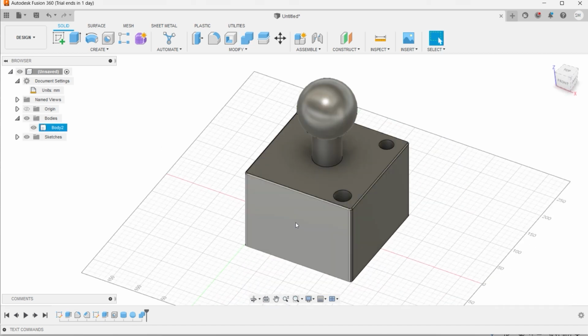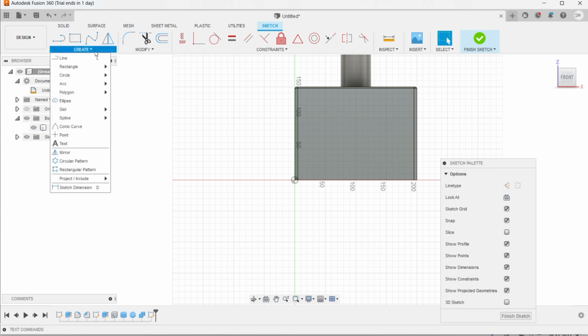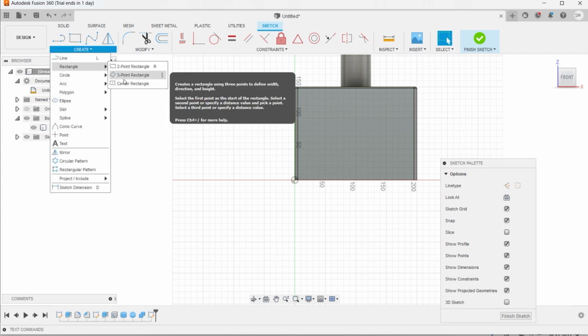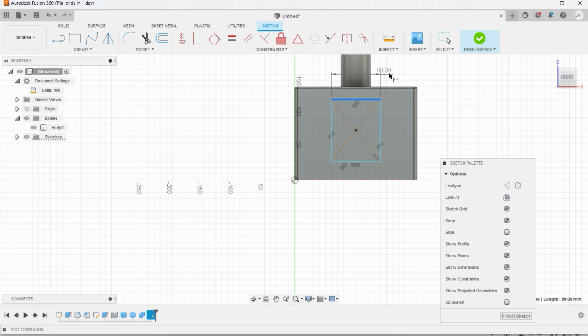Suppose you want to make one object here itself. Let us select that space and start sketching on the surface. I want to make one rectangle. It will be center point rectangle. You can make anywhere else, right? We made this one, and we can put smart dimension to this one with a D. This one equal to 80 millimeter, and again this one can be 90 millimeter. We have provided both the dimensions, but the sketch is not fully defined because the color is blue.